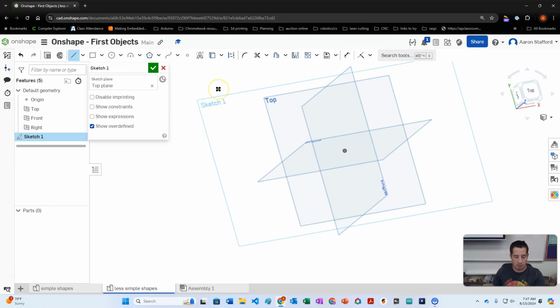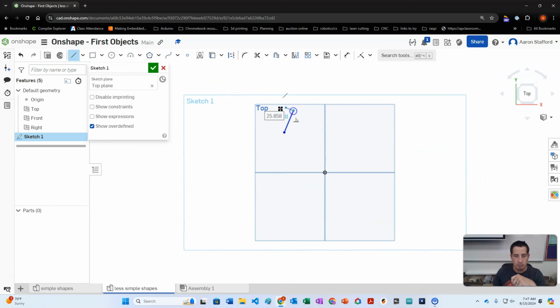And so this one, I'm going to press the letter N, and maybe I draw some more funky patterns here. Do you notice like sometimes things highlight when I'm drawing them? Those are what are called constraints. We're not going to worry about those yet, but they're a really important feature, and they're also kind of a headache when you're starting to learn. And so here I've established unintentionally a horizontal constraint between these 2 dots, which means if I move this dot up and down, that one's going to move with it because I've constrained them horizontally together.